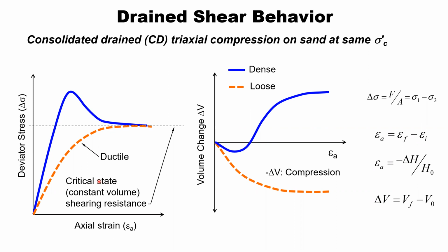If you go through this exercise, you can see that first they look for somewhere to contract. During this process of looking for somewhere to contract, it starts to generate shearing resistance as those particles try to move past one another. As the soil finds that it has nowhere left to go, it tries to ride up and over its neighbors. So during this process, there is expansion or dilation of that volume of the soil structure.